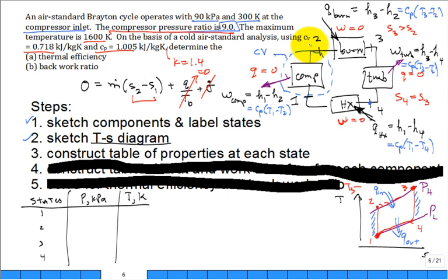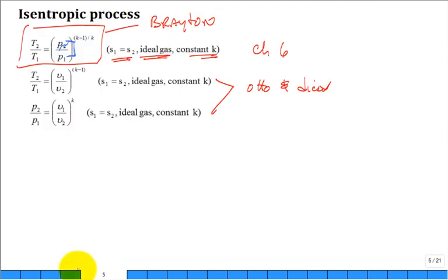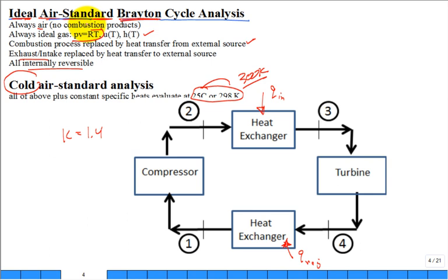So, is it wrong to write C sub P delta T for the compressor when the compressor is obviously not constant pressure? You see that it is conceptually a little challenging. I never said thermodynamics was easy. Sometimes it can be a little like, this doesn't make sense. But you go back to what an ideal gas means. Maybe it's back here. What are these three things? Why did I write three things when I said it behaves as an ideal gas?